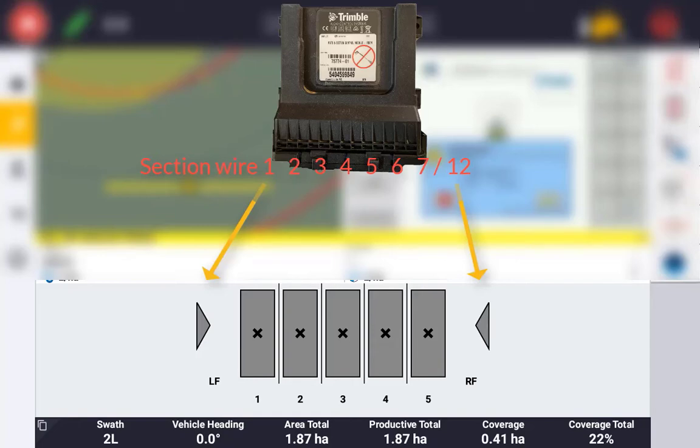Because of this, even though your vehicle may not be fitted with fence row nozzles, you may find that you need to tell the system that it has both installed. The most common sign that this is the case is you will find that the sections are offset by 1. For example, section 1 is not turning on, and when section 2 should be on, section 1 turns on.